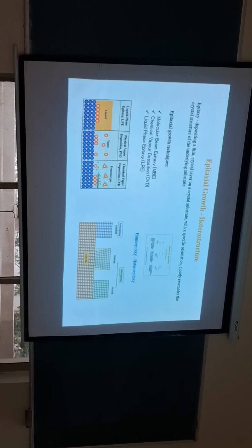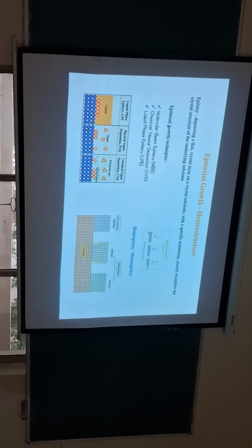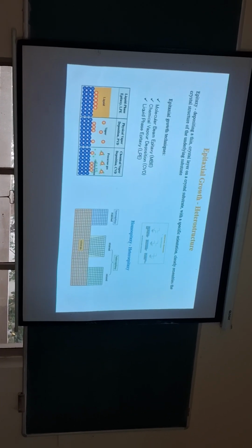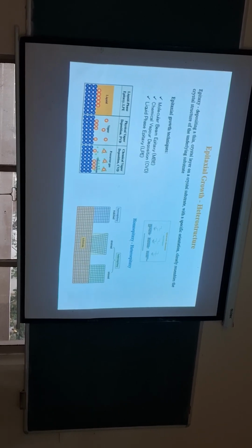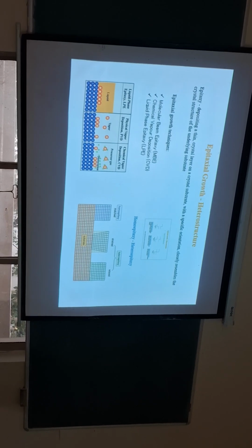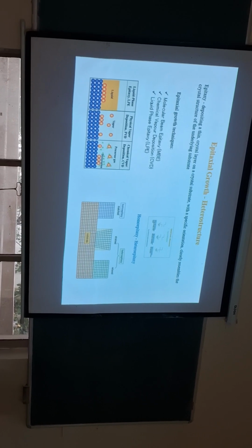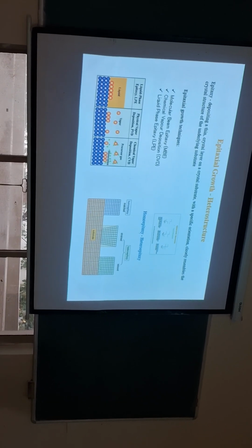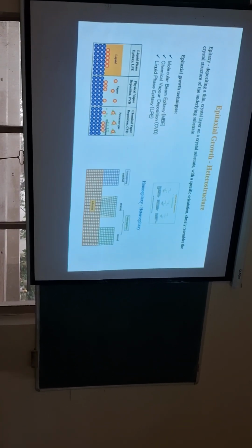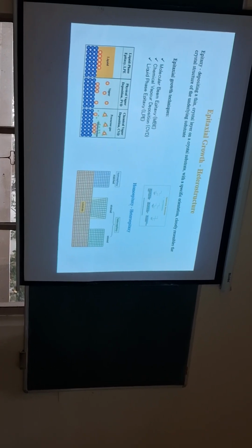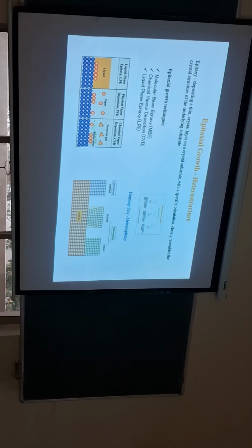We get a heterostructure which forms a potential well which populates the two-dimensional electron gas. This can be achieved through epitaxial growth of AlGaN over GaN, through molecular beam epitaxy, liquid based epitaxy, and vapor based epitaxy.